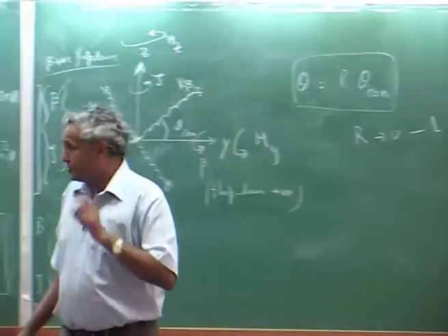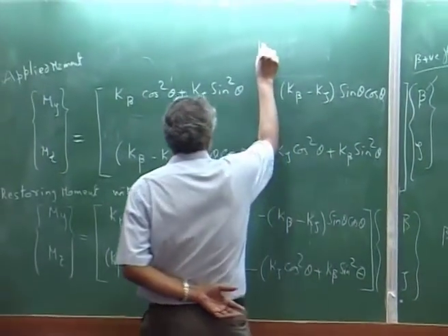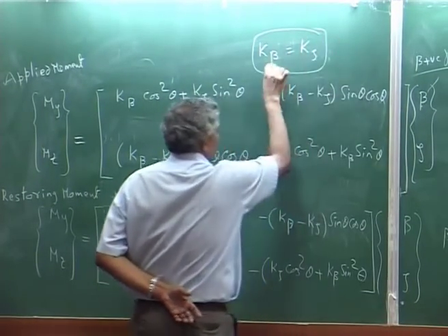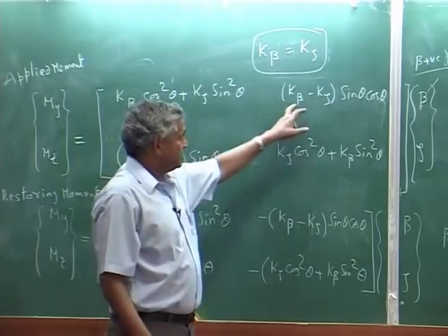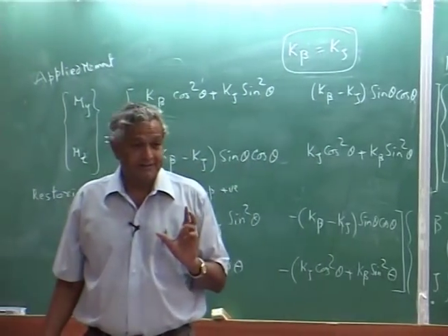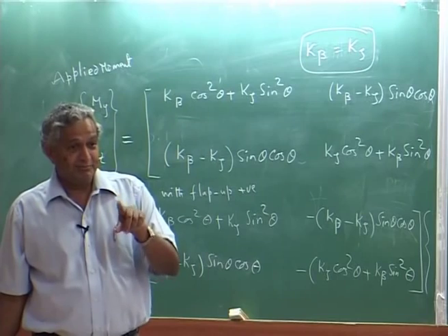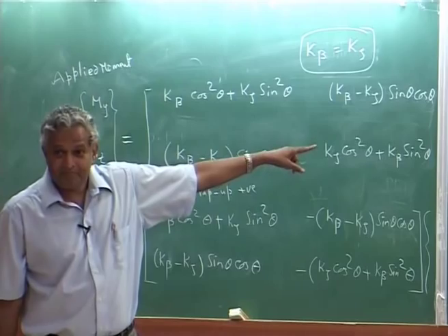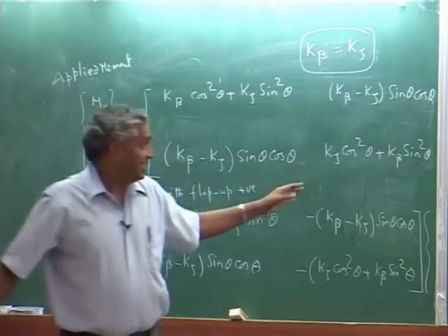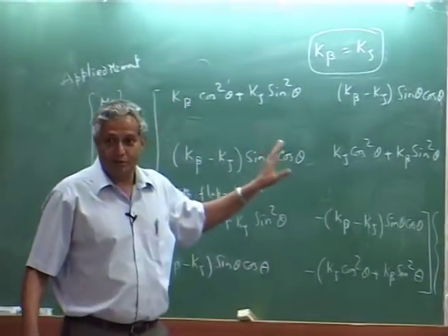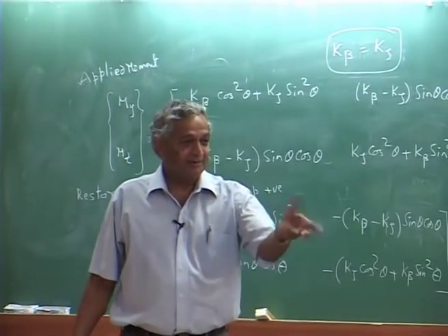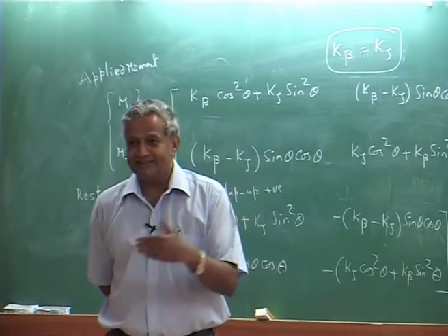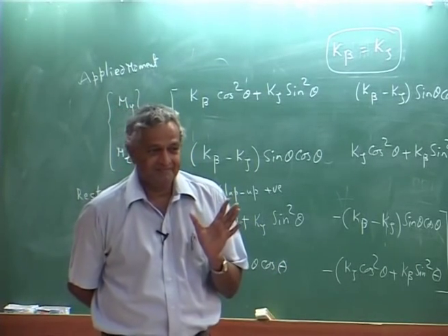But if you introduce k beta equals k zeta, that means the flap stiffness is same as lag stiffness, that is the structural stiffness of that spring assembly, then I do not have any coupling, no matter what the rotation, whether pitch bearing is inboard or outboard, does not matter.